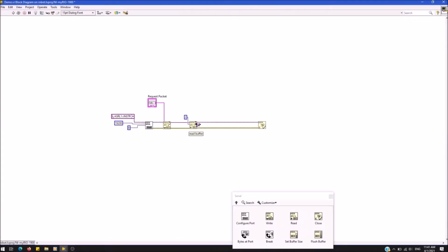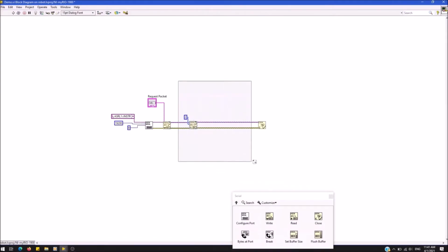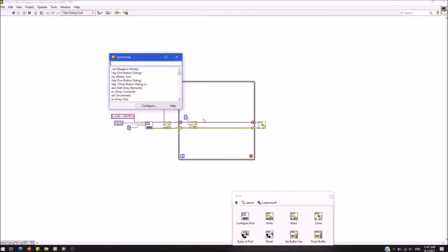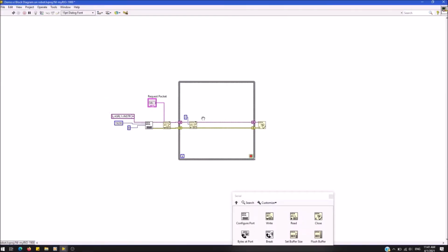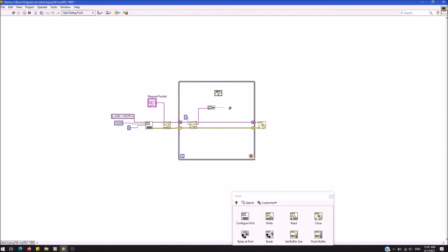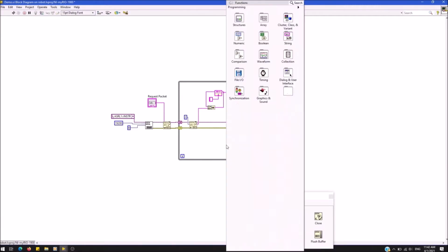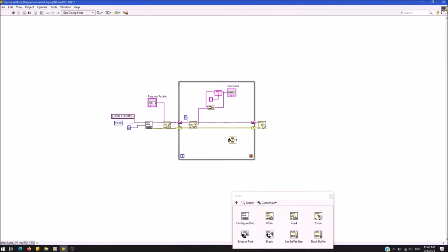So just to show you how the data is being received and flows, I'll be using a while loop to show you how the data for every 2 bytes is being generated. In this, I'm also using a feedback loop, as well as concatenate string to form the whole raw data. Here let us put a wait of 200 milliseconds, as well as a stop to control